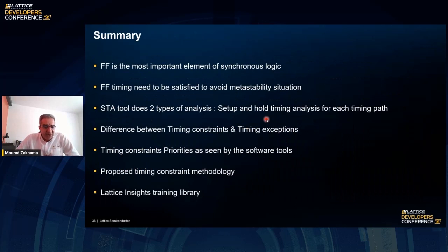So as a summary, we've gone through the flip-flop, which is the most important element in synchronous logic. We looked at the meaning of metastability and how to avoid that situation, the STA process, and the two types of analysis conducted by the STA tool, setup time and hold time analysis.